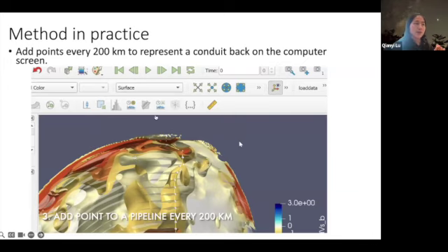And with the help of the VR interface of ParaView, I'm able to crop everything at one time. So whenever I need to slightly change the orientation of my crop plane, so I will be able to better see my conduit, it is done automatically in VR. Versus if you're trying to do it on a desktop version of ParaView, you need to apply it all again to all the spheres you have here. And you can imagine how time consuming it would be.